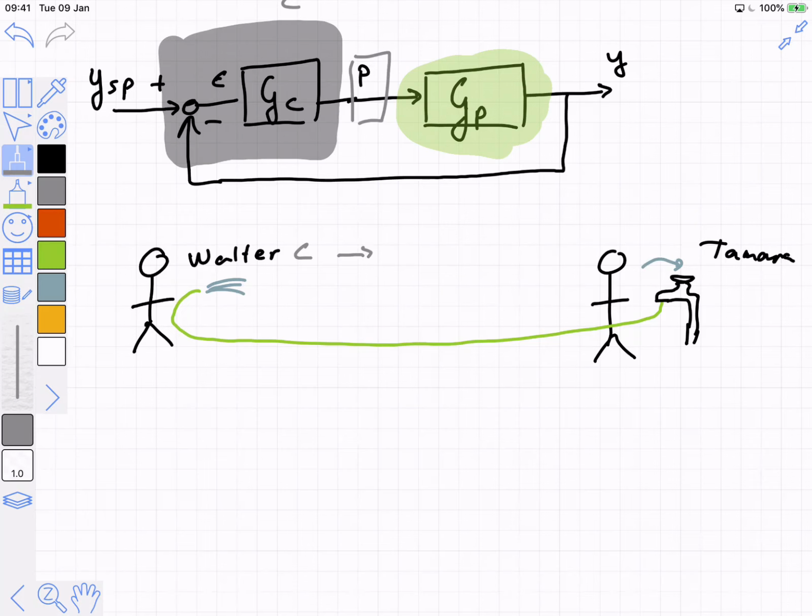Okay, so this would effectively be the valve if you were talking about a normal chemical engineering control system. The controller doesn't actively immediately change the valve, right? It gives commands to the valve. It can change a pressure signal, for instance. The valve itself also has dynamics. It doesn't immediately move to a new position. It accepts the commands and then tries to follow them.